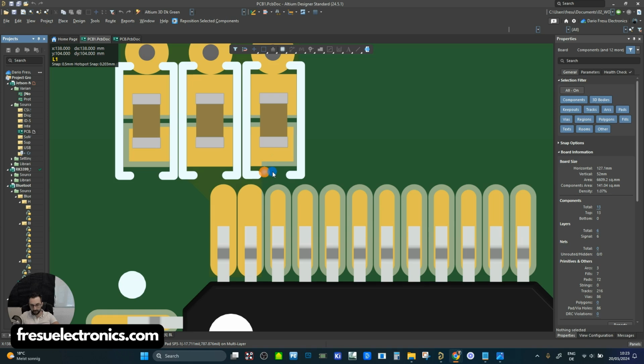And then we also have the inductance of the pins, which of course we don't have much control over. So as a designer, we really have only two parts that we can control. One is the inductance of the package, which we can choose by selecting a different package. The other is the inductance of the traces, which we can control by designing different geometries of our traces. And this means that the layout itself will become very important.